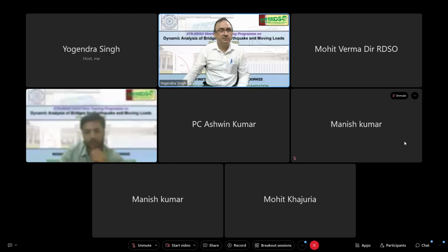Okay. Mr. Lalit is asking, while doing response spectrum analysis for closely spaced mode shapes, shall we do CQC for modal combination or directional combination? What is this directional combination actually used for? Okay, so earthquake has 3 components. Earthquake rather has all the 6 components. So during earthquake, the motion at a point has all the 3 translations and all the 3 rotations. All 6 types of motions are there.